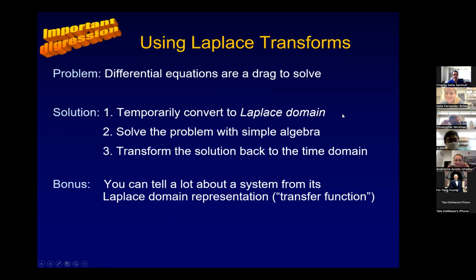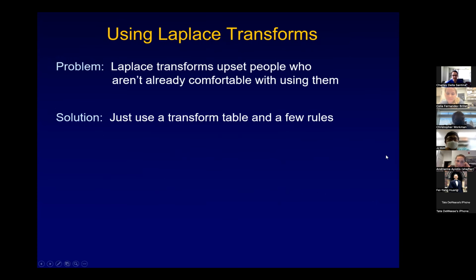And in fact, you make life easier because instead of dealing with differential equations and trying to solve that in the time domain where it's a drag, what we're going to do is we're going to cheat, and we're going to transport ourselves into the Laplace domain, where all of the complicated differential equation stuff becomes just easy algebra that we remember how to do from junior high school. And then we'll get the answer, and then we'll transform back into the time domain. And this is how you do Laplace transform analysis or linear signals analysis.